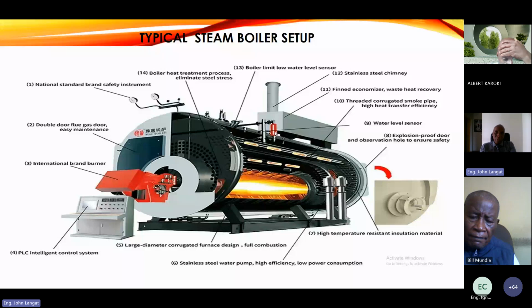But if you adjust the level slightly lower, and normally those guys are trained, any boiler operator operating a boiler in any establishment ought to have had this training. For KTDA, they normally take their people to NITA trainings, specifically to be trained on boiler operations. These are basic operational issues. So whenever you're auditing and you realize the water level is high, that's obviously a red flag. You note those as operational recommendations that can be achieved without incurring any cost.